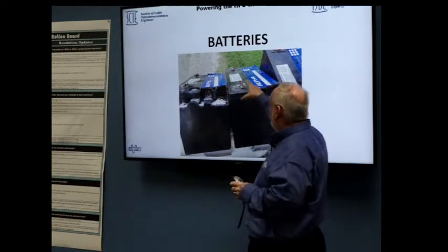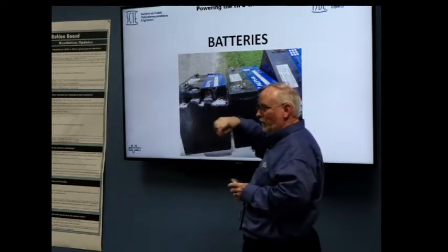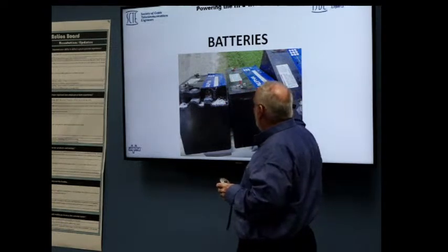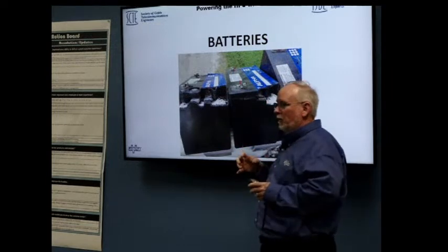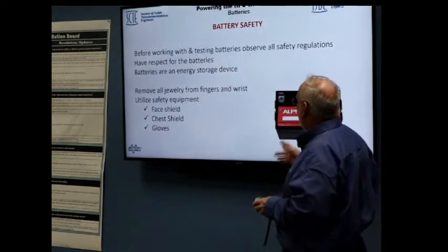Inside here, there's a circuit. And when I say circuit, it's not electrical. It's actually a mechanical venting circuit, which allows the batteries to outgas if they need to, but it's regulated. So they're sealed for all practical purposes.